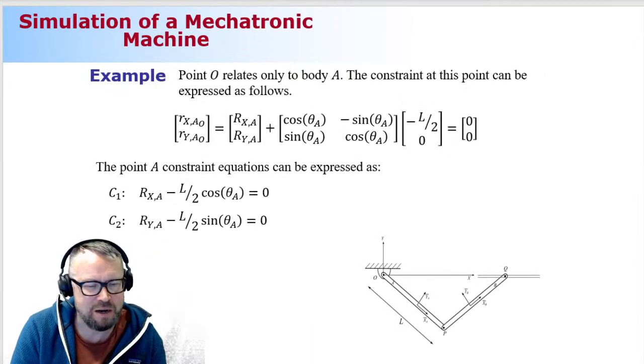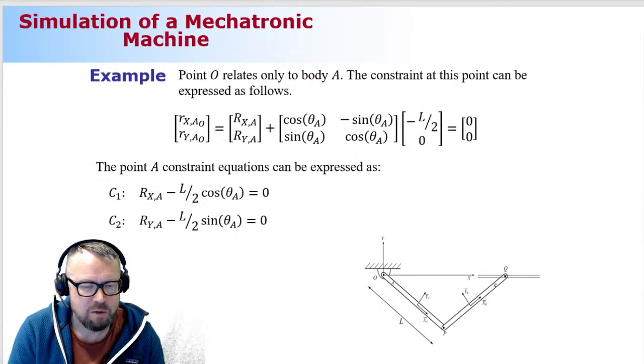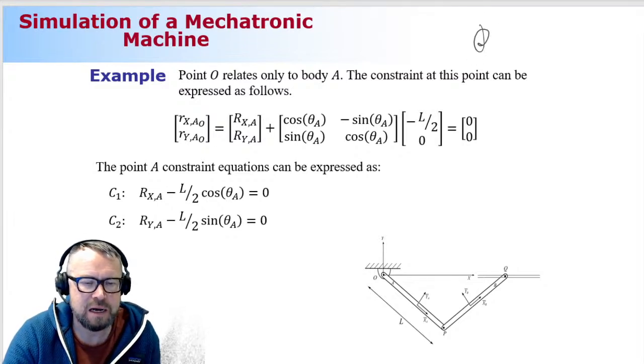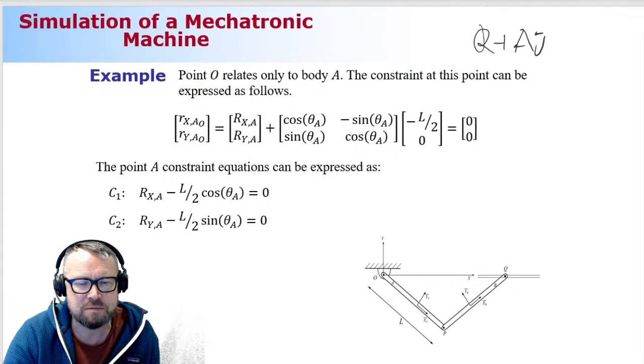All right. So how can we introduce these constraints then? Okay, it's simple business. We can make use of this equation. It means that even though the first revolute joint is located here at the origin, we cannot make a shortcut and stay here. We always have to start from the origin of the global coordinate system. We need to go to the origin of the body reference coordinate system, take the orientation into account, and come back with the help of u-bar.